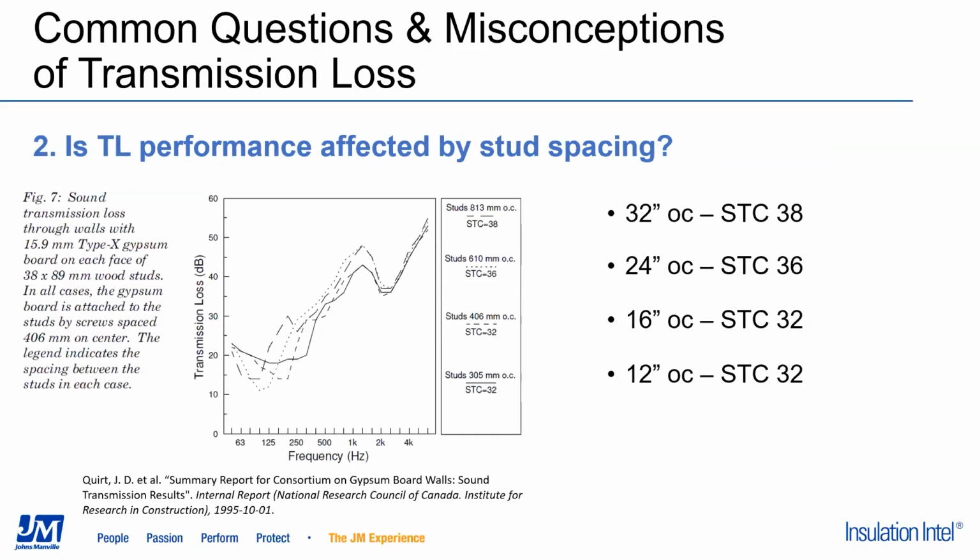Is transmission loss affected by stud spacing? So this is taken from a study that was completed by the National Research Council of Canada. And we're looking at a system that has gypsum boards, and we have 2x4s installed, and we're just looking at the spacing that they attached their studs down to the top and bottom plates. On the right, you see a breakdown of what these ratings look like. So they started with 12 inches on center and went up to 32 inches on center.